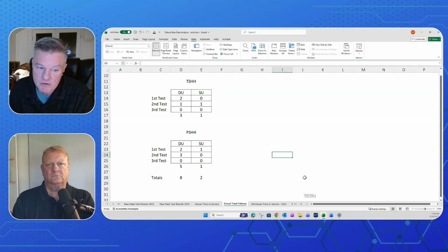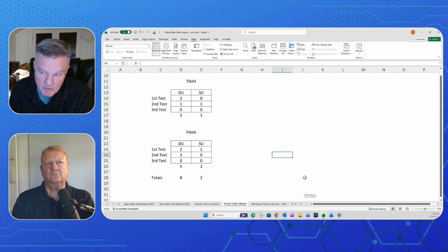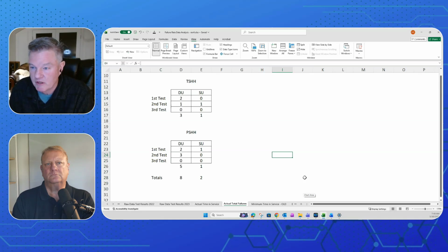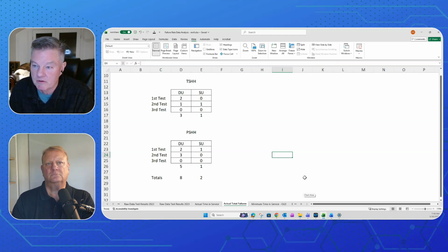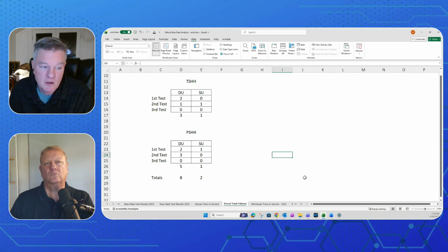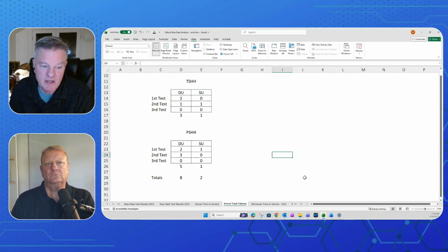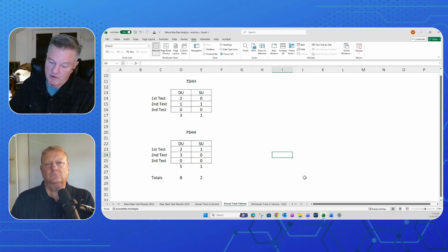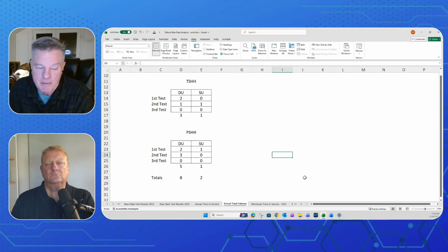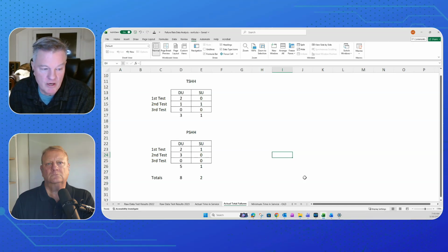Same thing with the test intervals. I can bulk edit the test intervals and make them 12 months, 24 months, 36 months, and all 500 calcs just magically run, and we look at pass fail. So it's very rapid having this failure rate, not having to go into individual calculations and change it for transmitter A and transmitter B and transmitter C and valve A and valve B and the logic solver. All that is bulk editors.